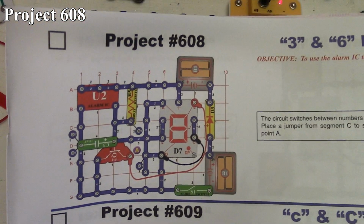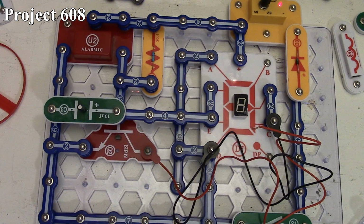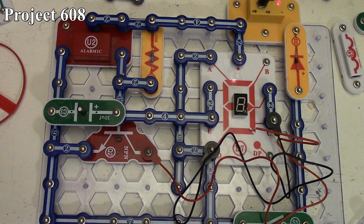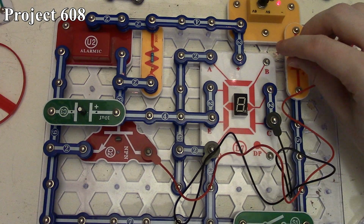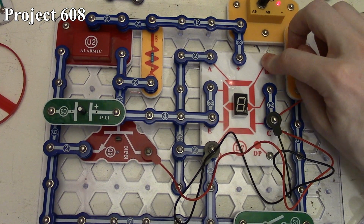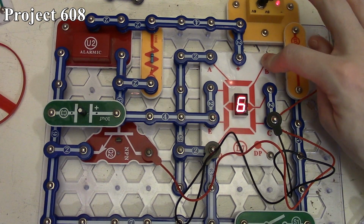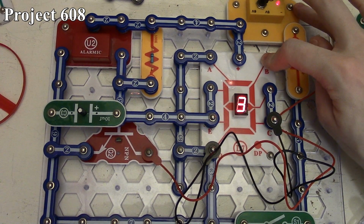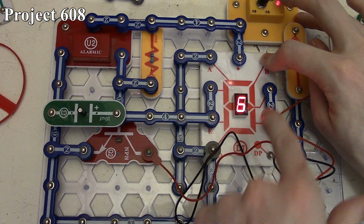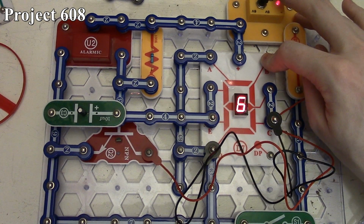So here we have Project 608, the 3 and 6 blinker. There it is in the book, and here it is on the board. So again, as usual, we just reroute some connections there for our 7-segment LED. We don't have our A1 antenna coil anymore, so when we turn the circuit on this time, it now alternates between showing us a 3 and a 6, again as our alarm IC drives our NPN transistor, turning the output of that on and off, controlling the B segment of our LED display here.